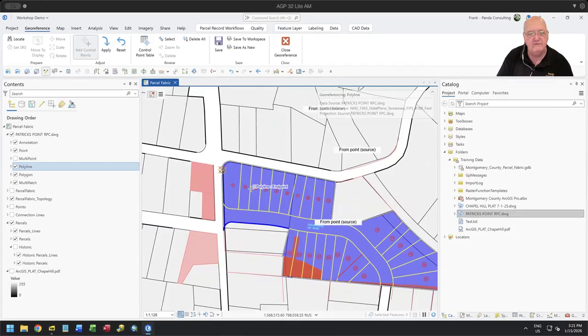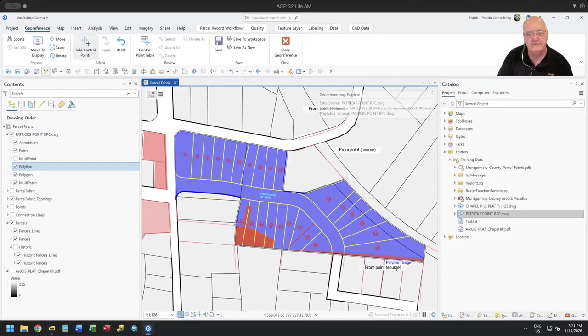With a CAD file, again, you only get two points and you have to tell it to apply that. Now I know that our GIS data right here isn't as well situated as I would hope for, so I'm actually warping the CAD file to try to fit it into the GIS data. But this was a pretty good CAD data set that we had, so I normally wouldn't do that.